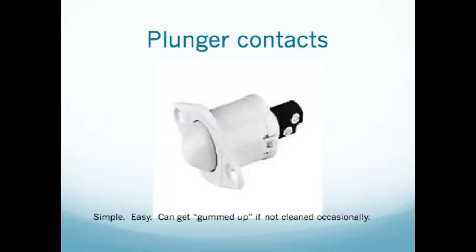Now we looked at different types, well, not all the different types by any stretch, but we looked at different types of reed switches, and we looked at the primary ones you would use. But there are also different types of contacts. This is a plunger contact. So you mount this somewhere and a door will come and close on it, right? And pushes this little plunger in. This is just a little ball here that's on a spring, and there's a little switch down here.